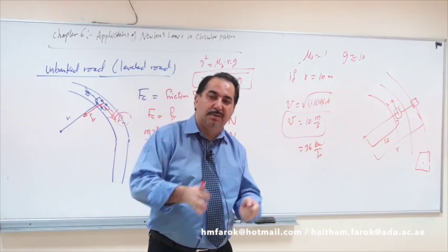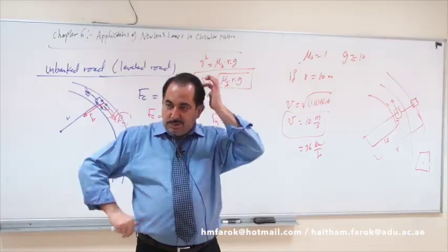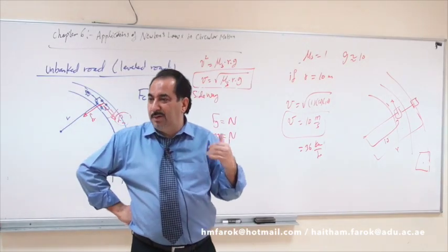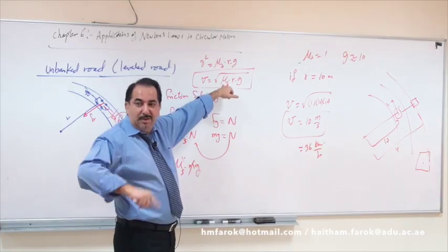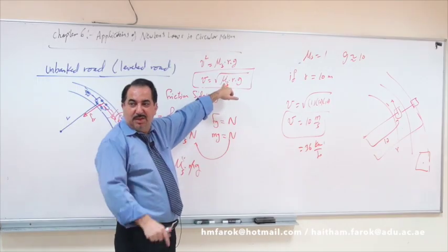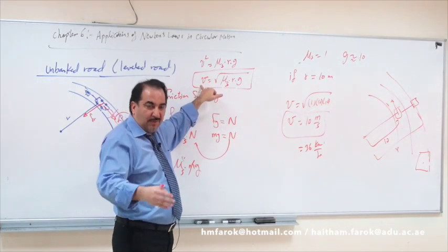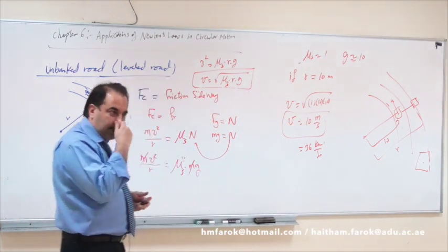When you turn the car, will you be able to, or does it slide off, yeah? So the engineers thought of a new design, which doesn't depend on friction. Or when the tires are old, mu will go down, like 0.1, yeah? So the smaller the mu, the smaller the maximum speed, yeah? So you have to come slower to avoid sliding off the center.